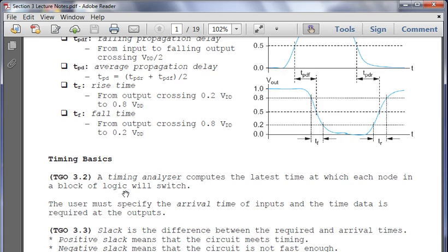And based on the delay, you're going to be able to tell the longest, what's known as the critical path, which is the longest delay through the circuit. Based on that critical path, you have to make sure that all of your signals time properly. For those of you who've done advanced design, if a signal gets to another block before all the other signals do, it causes issues.